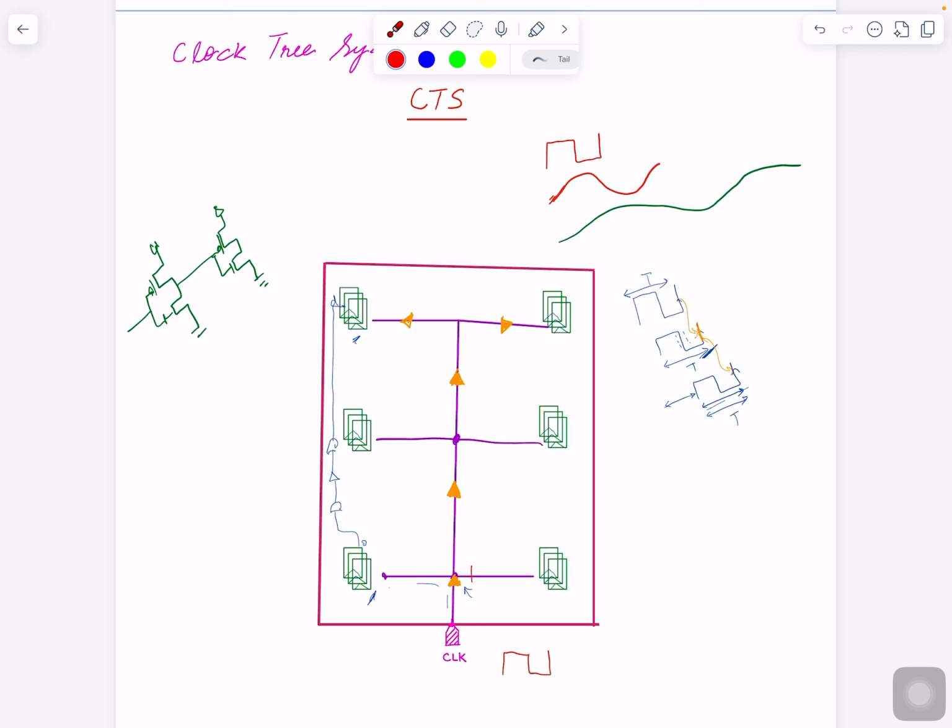So you see the problem with buffering them just for transition time and shape might create a problem for delays. So what you want is this point here or this point here, this point here, you want them because you don't know. I mean, you don't open the design and figure out which flops have a valid path between them and which ones don't, or only balance those ones.